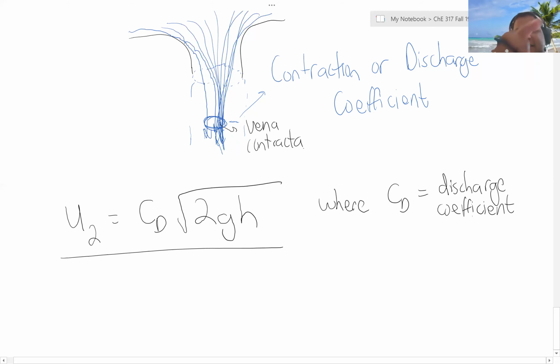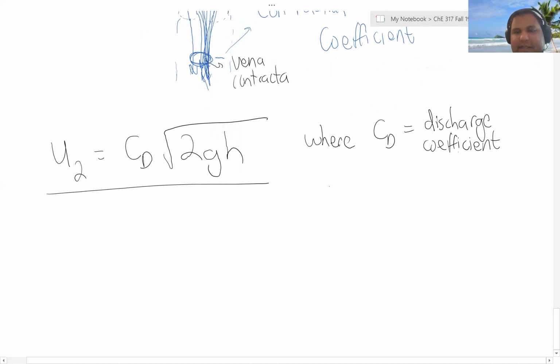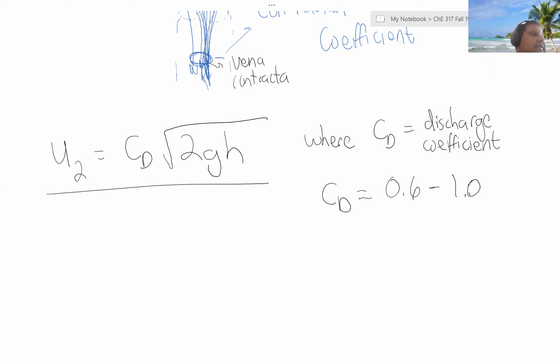It just states that the flow doesn't occupy the entire outlet in most systems. And the actual discharge coefficient can vary typically between 0.6 and 1. And it's largely a function of the geometry of the outlet itself. Things like sharp-edged orifices have low coefficients of contraction, and well-rounded orifices have high values of discharge coefficients.